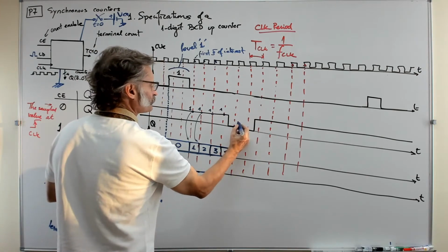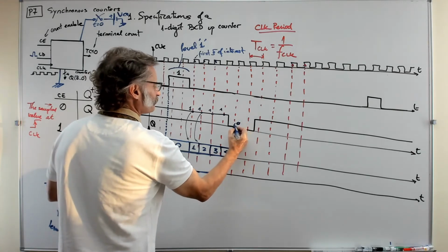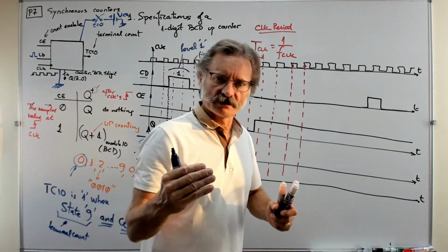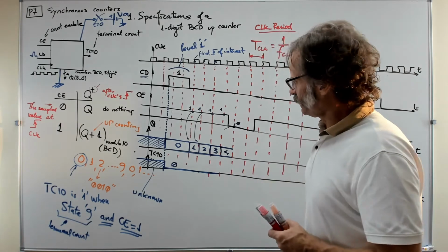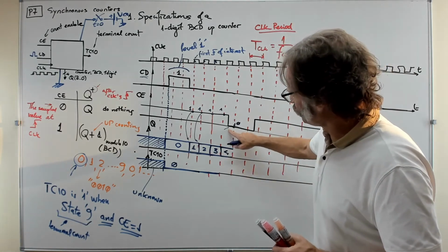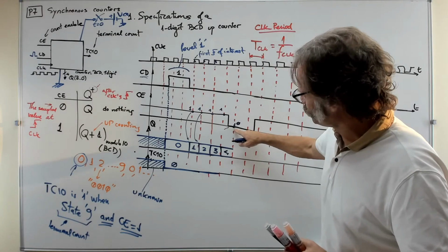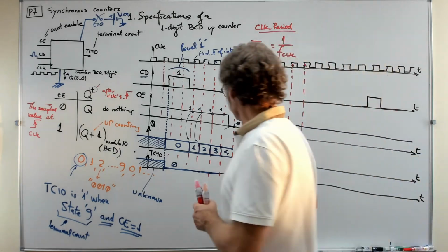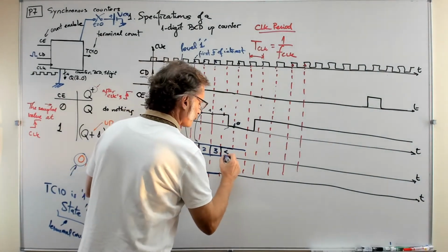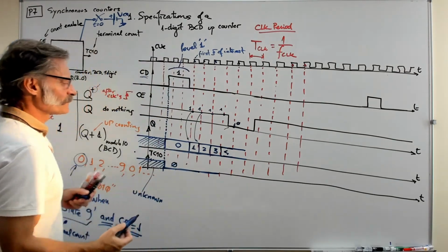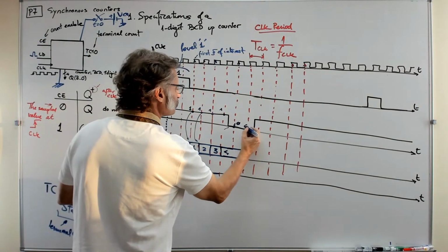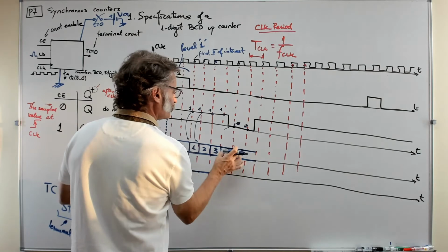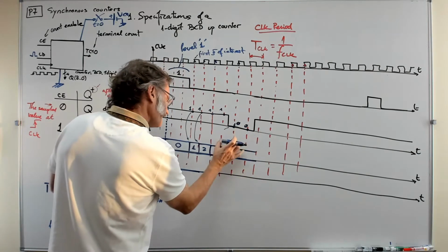But now what happens? You see, you are sampling a 0. Be careful with this. You see, the level 0 has started here. But you are not aware of the level in the control inputs. You are aware not of the level, but only about the value that you are sampling. And here, on the rising edge, you are sampling a 0. So now is when you just repeat the 4. This is the meaning of not letting the system count. You repeat the 4 even another time, because again, you sample a 0. So you see, the 4 is kept for all these 3 perfectly right clock periods.